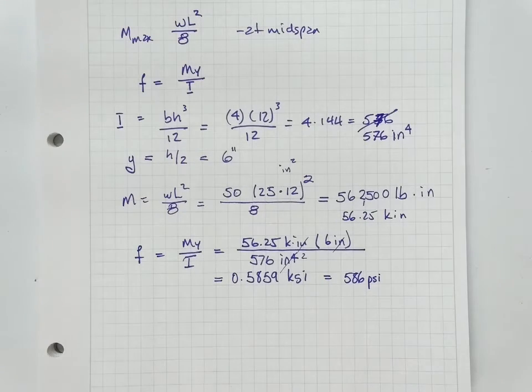Did you break any samples on the compression machines? Remember, you would take the load, it would look normal, and it would go bang, right? It would all of a sudden be shattered. Now imagine that beam, 50 pounds a linear foot, 25 feet, 15 feet above people's heads while they're taking the forms off, does the same thing. Instant failure. Comes down without warning.